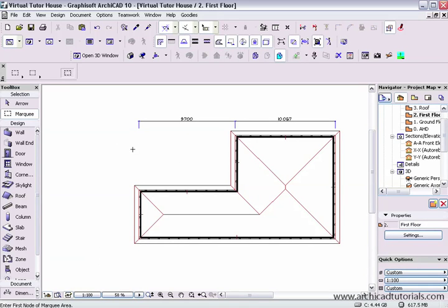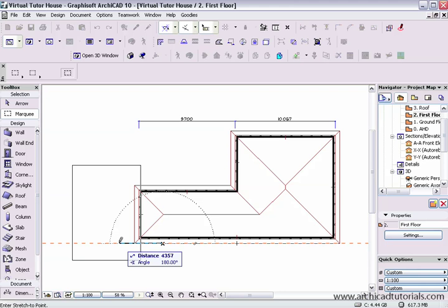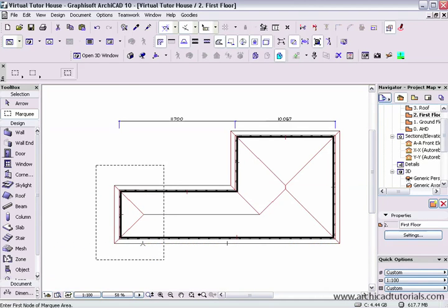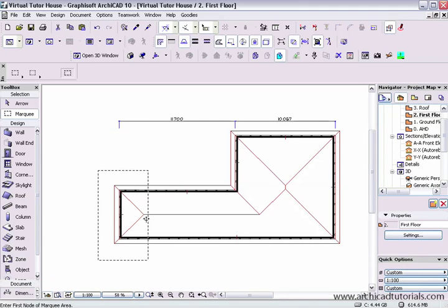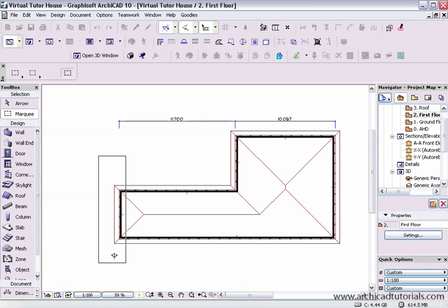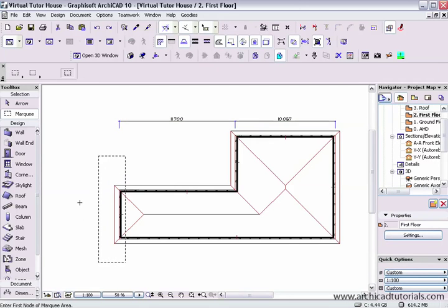Conversely, if I wanted to stretch it by 2 meters, when doing this, we have to be careful that if we stretch the roof, make sure you're behind the ridge, because if you're not, the results can change. Control H can change the angle of the hips like that. So I'm just going to go Control Z to undo that.